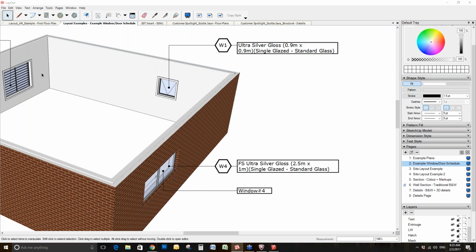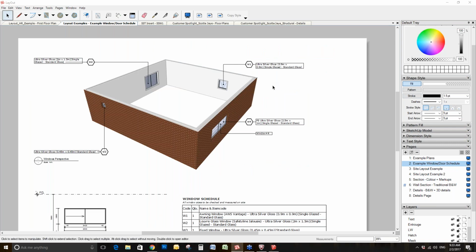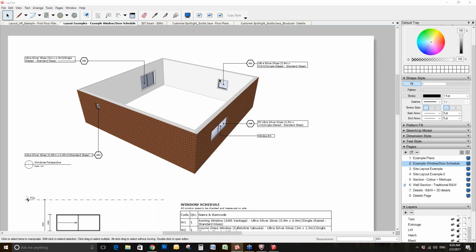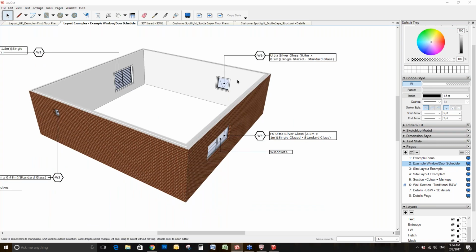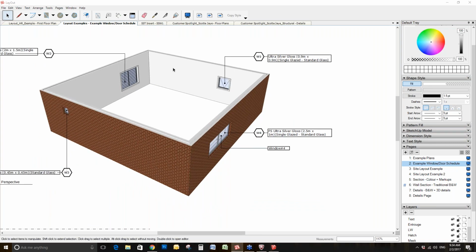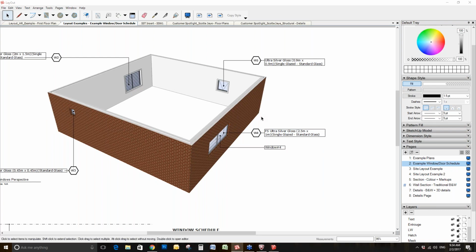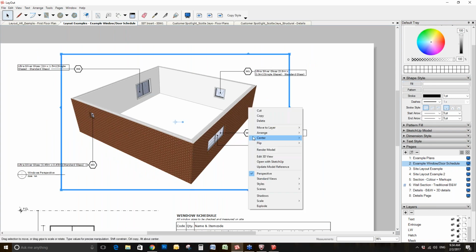It is important to note that in 2D documentation we obviously like to have the windows and doors going in an order, typically clockwise. This is the window that I drew first inside of PlusSpec. But if I drew another window over here and then deleted it and then drew this window, it will be called window number 3. So you can edit these things also, and I want to quickly show you that.